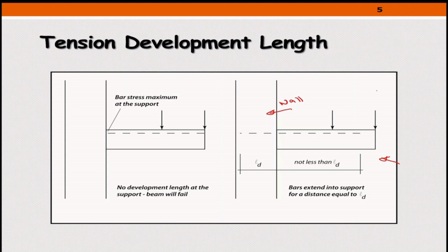And we can easily identify this system to look like this cantilever. We understand that the bending moment at the connection between the beam and the wall is actually fixed. Due to the fixation, here is actually negative bending moment, which is this here, negative bending moment, that would require reinforcement at the tension side, which is the top of the concrete. So when designing this section here, we make sure that we provide the reinforcement needed to resist M negative here.